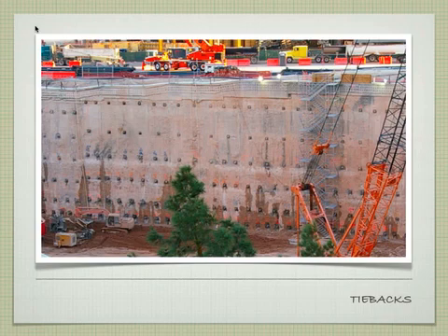Will you use any of the temporary bracing with the slurry wall? You can, and you may do it sometimes as you're digging if you need that temporary bracing. It's designed so that theoretically, if you dig only this much, then you put the row of tiebacks in, you shouldn't need it, which is a big advantage when you're working on the site because there's nothing hindering your excavation of the site. It's easy to work in that site itself, which is the big advantage.